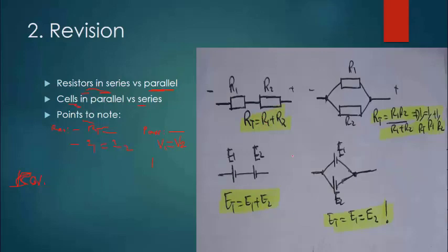that the effective voltage in this connection is equal to E1 plus E2. Now here, remember, if one of the batteries is reversed, then it should be assigned as a negative electromotive force, because this is a force, so it can be positive or negative depending on the reverse direction or the forward direction. So if either one of these batteries is reversed, for example if you flip battery E2 to face this way, then here there will be a minus. So the general formula is E1 plus or minus E2. Just remember the directions of the cells matter a lot.